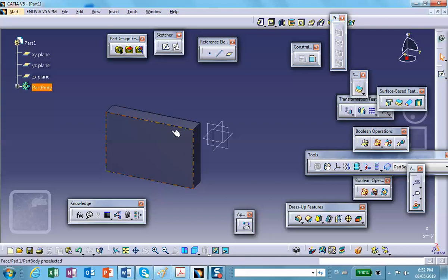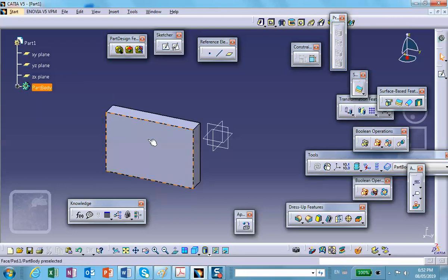There's two ways to let this thing go. Either you put the cursor back on the white branches and click on it, or you go to this coordinate system down here and click on it. Now you have it at your disposal. The other thing is the F3 button. F3 button hides and restores the tree. Okay, good. So if you don't see the tree, try F3.